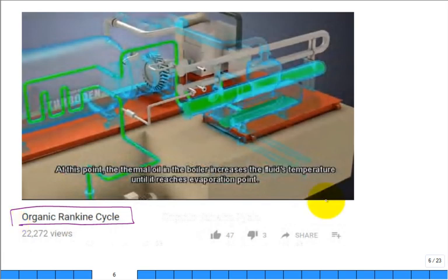Here in this video, if I watched it recently, they basically have a burner, and they heat up oil, and then they pass the oil over. Hot oil comes into the cycle, and then that oil is used to boil or evaporate, if you want to call it that, but it's really boiling a refrigerant in an evaporator. And I've seen where they have taken compressors and tried to run them backwards with small modifications, things that are typically in the air conditioning, refrigeration business, and adapt it for power production.